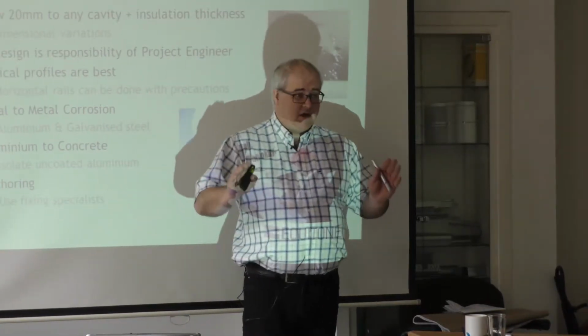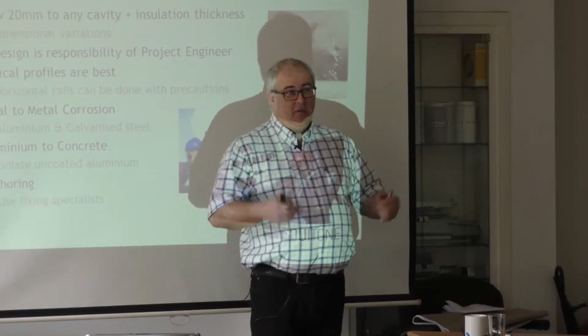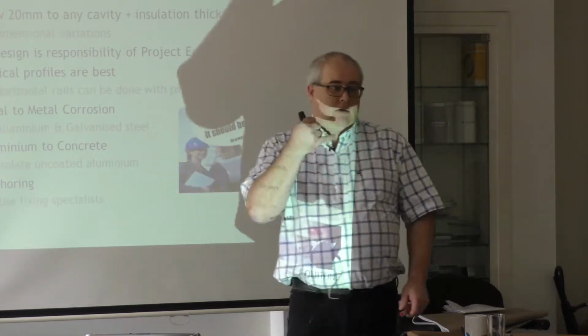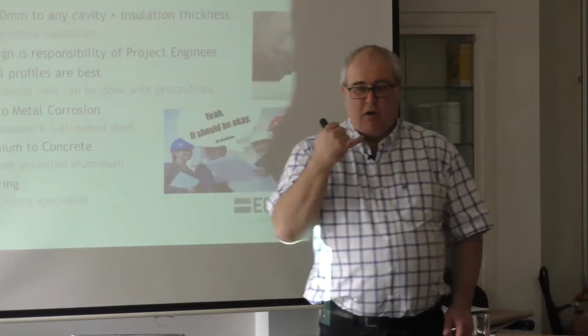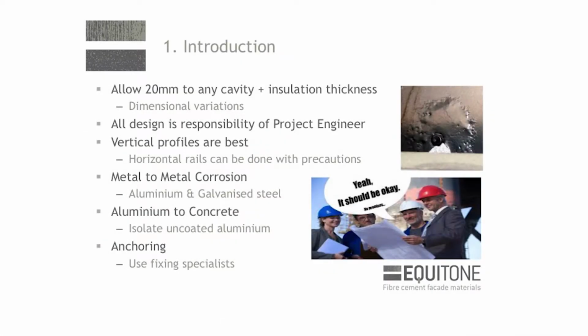The guys who are physically doing it on the job site must understand you're not to be mixing metals together. You cannot have aluminium rivets fixing to galvanized framing systems. Okay? I have seen it all over the place. Oh, there's a box of rivets in the van. Let's bring it out. We can fix away on them. Let's use them up. Okay? Ding ding. Oh, we've had 5 panels fall off the wall. Your problem, not mine. So be very careful with that.